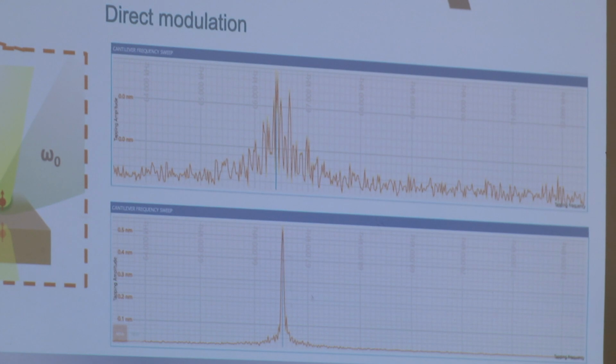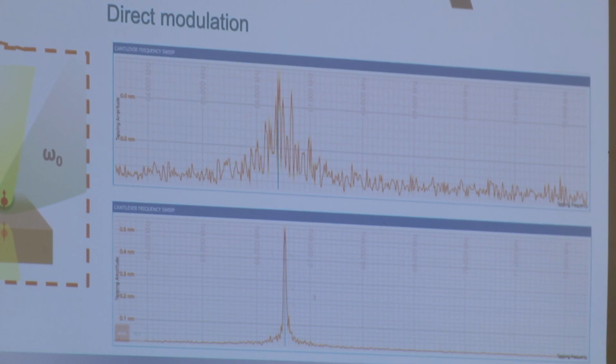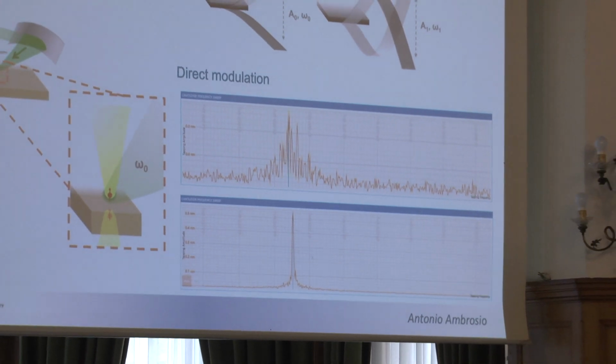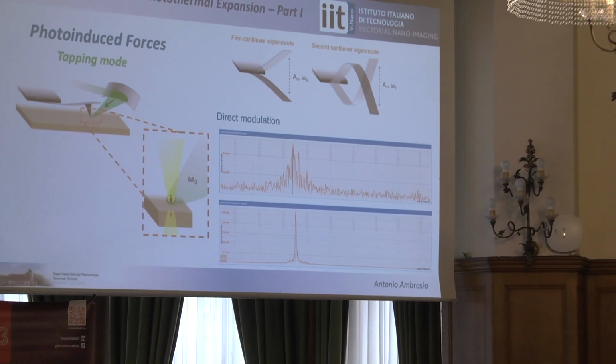It's actually another way to drive the cantilever oscillation. It's called blue drive by Bruker. It's an alternative to the mechanical transfer from the piezo that can eventually help to improve the signal to noise ratio in some measurements. But I just want to tell you that, of course, that's not the way, right? It will enhance whatever background from the cantilever there is.